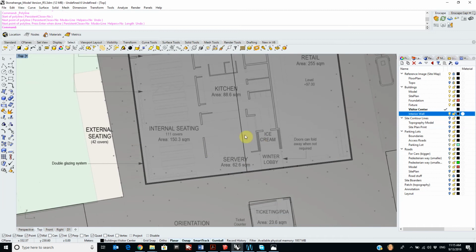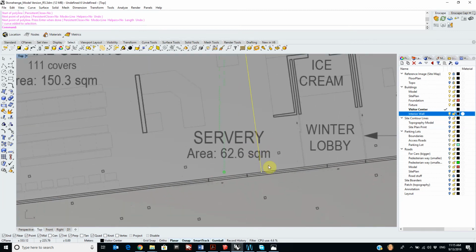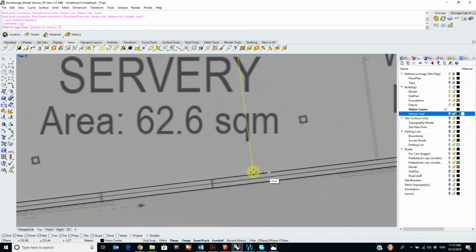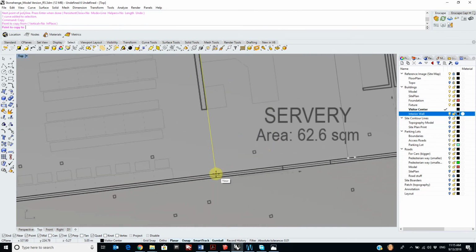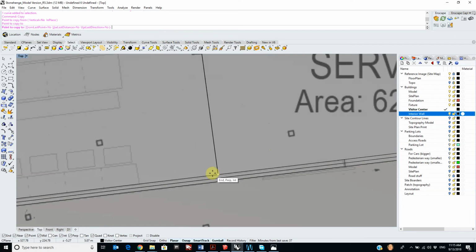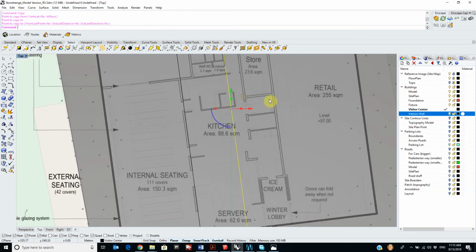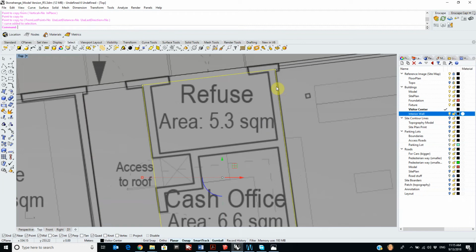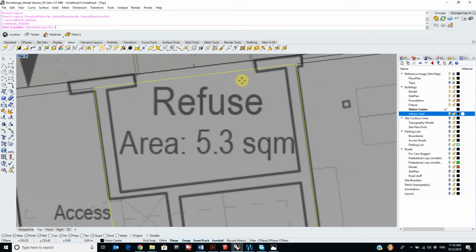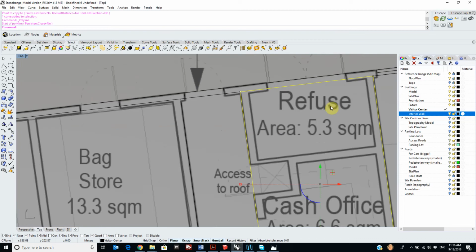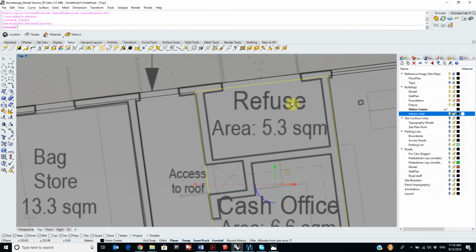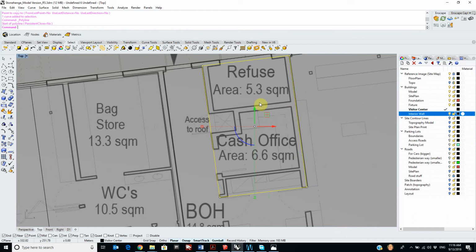Let's try it here. I'm gonna do copy command to bring it to here. We know the thickness of our wall, so I do not have to draw it again. Okay, that one seems to be correct. We just need a couple of things here. Okay, let's explode this rectangle that we have, deselect this. We don't need that one.